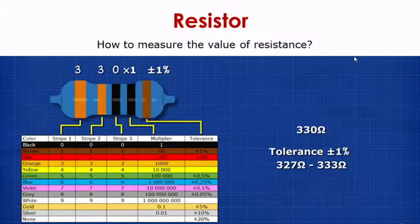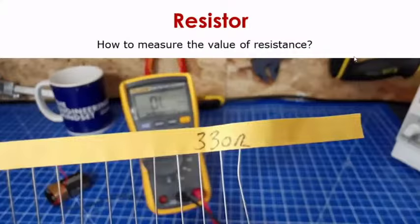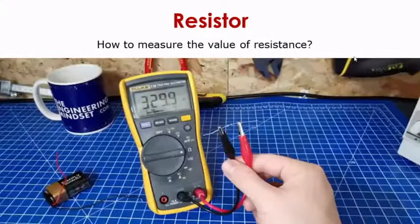So the value varies from 327 ohm to 333 ohm. Let's measure the actual resistance value of the 330 ohm resistor using a multimeter. So it shows 329.9, so close to 330 ohm is the value of this particular resistor.